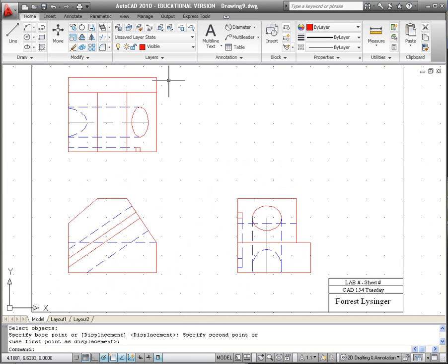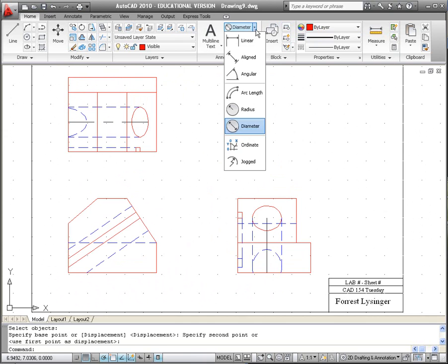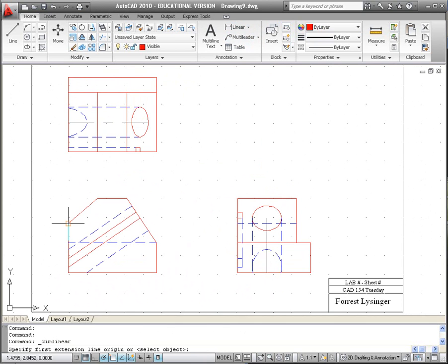So now when you place dimensions on this part, if I go up here and select a linear dimension, I have the corrected English dimensions for the features. So of course, select your layers, then go and redimension this part in English and see if you can find the setting where you would do a dual dimension for that. That's it.